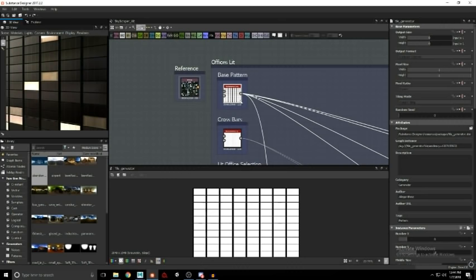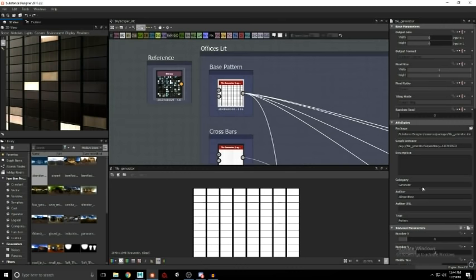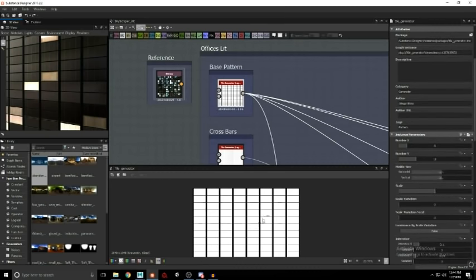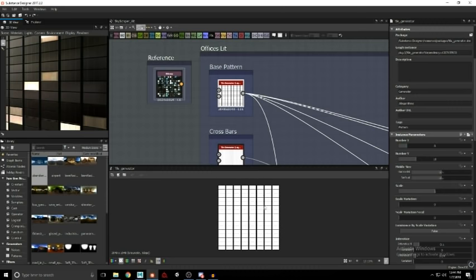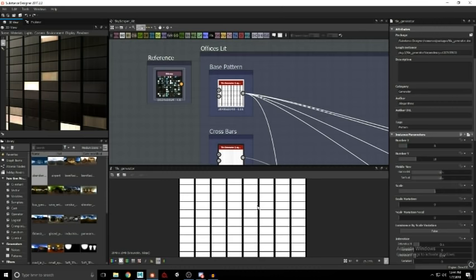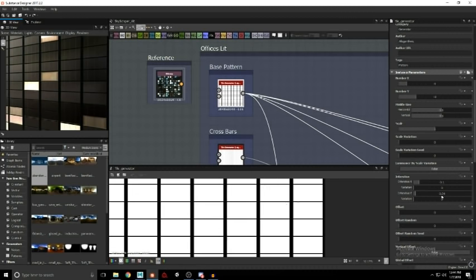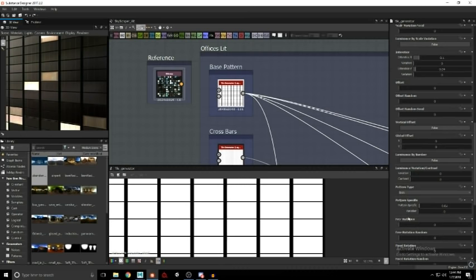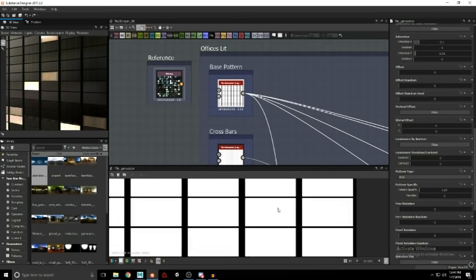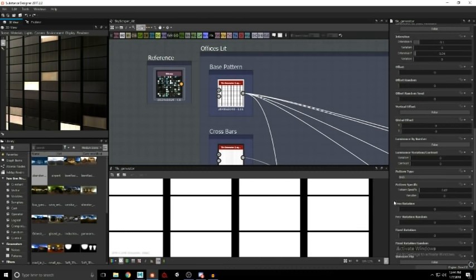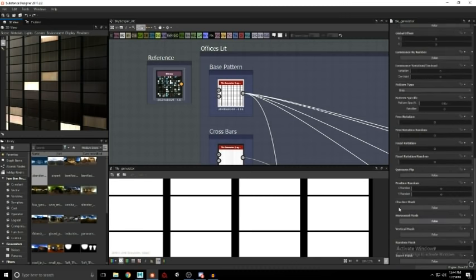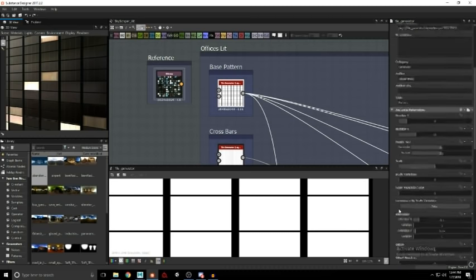We're going to begin with another tile generator. Lots of tile generators for this. 8 by 16 is our default pattern, so that is 16 down, 8 across. Then down here, our intersize X is 0.1, and our intersize Y is 0.04. That gives us this kind of separation. Pattern specific 0.02 gives nice crisp edges on things. And then I think that's it. We don't need any masking just yet.